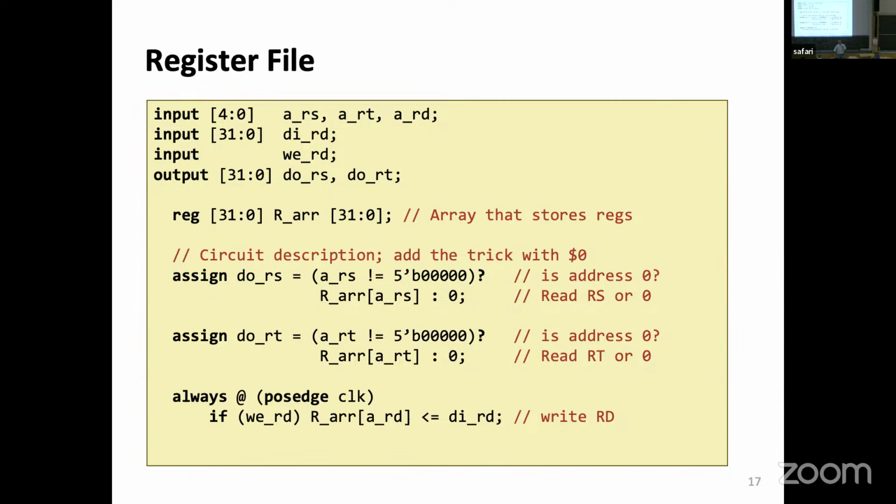Hopefully, now, the interesting question that you could ask, and it's a very fair question, is why do I not have an array of 31 instead of 32? The idea behind compilers and optimizations is that hopefully the compiler will realize that one element of the array is never being read and never being written to. So it just says, okay, if you never read this thing, nobody knows it, let me remove it. Optimization routines in modern logic synthesizers will be able to take advantage of that. You don't necessarily have to overcomplicate your life and write code that is less readable. It's much more preferable that the code remains more accessible and the optimizations are done by compilers rather than you taking things into your own hands.